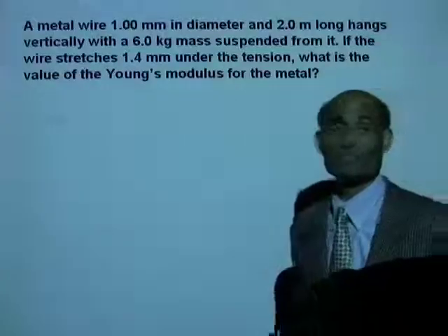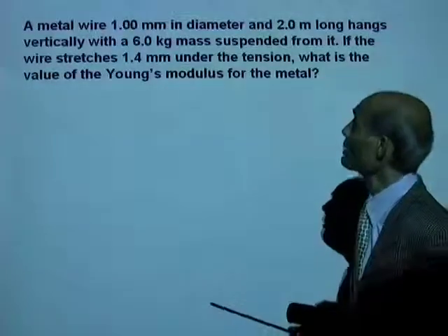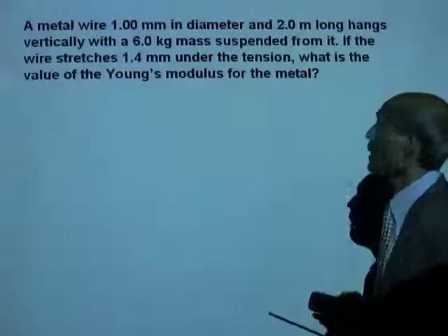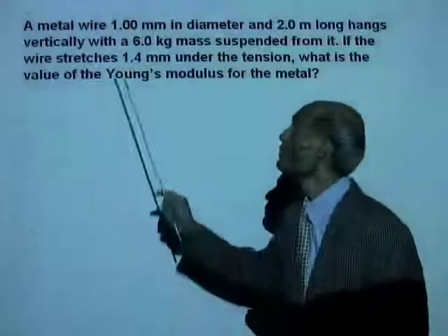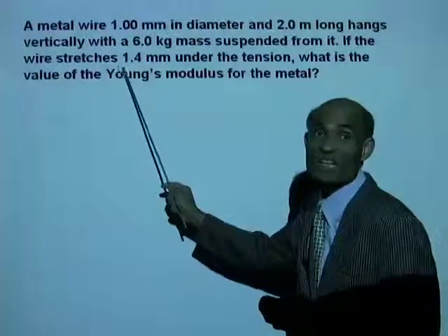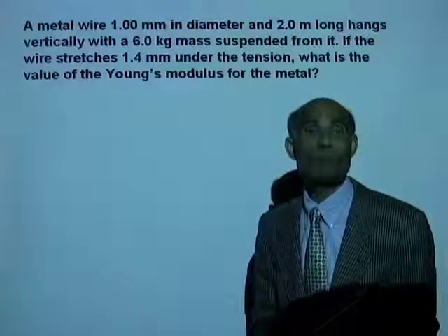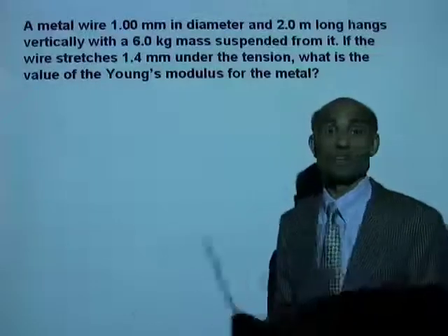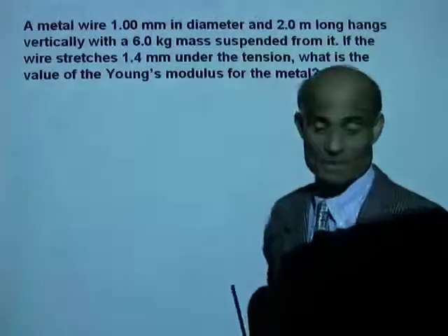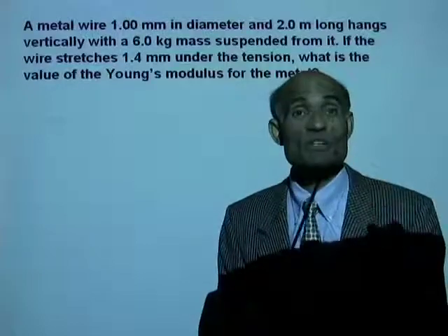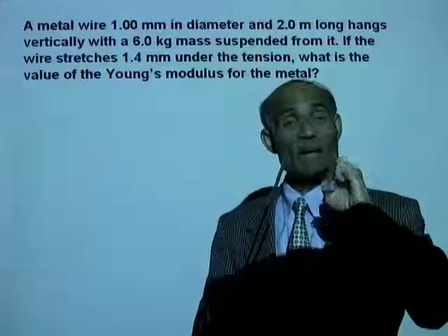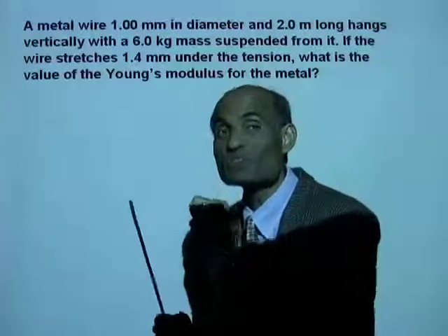Okay, let's do another problem. A metal wire 1 millimeter in diameter and 2 meter long hangs vertically with a 6 kilogram mass suspended from it. If the wire stretches 1.4 millimeter under tension, what is the value of Young's modulus for the metal? Well, to find the Young's modulus, first we need to calculate the stress, force divided by area. Then we have to calculate the strain.